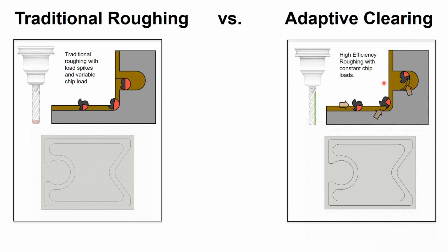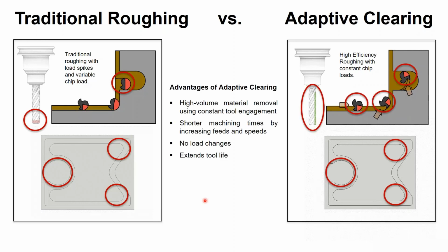And the same thing, instead of a full wide cut, we start to move the tool in rotational moves, and that will give us a very smooth and a very, very controlled way of moving the milling tool. So by that, we will remove the material much faster during machining, because we can increase the speed of the machine, because we know the cutting condition from the beginning.